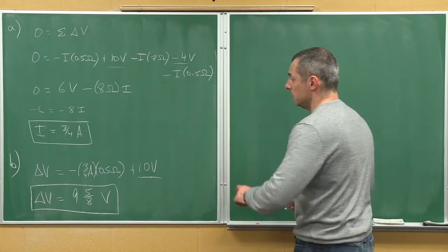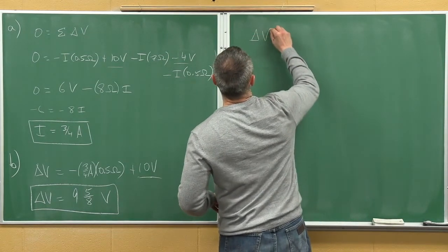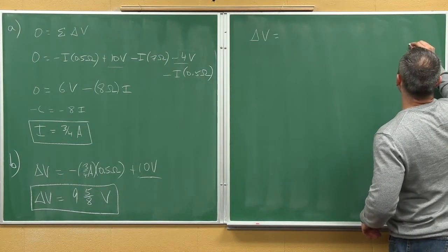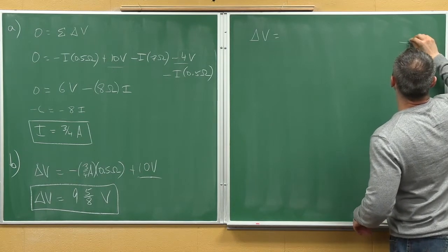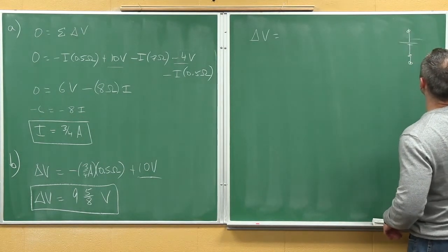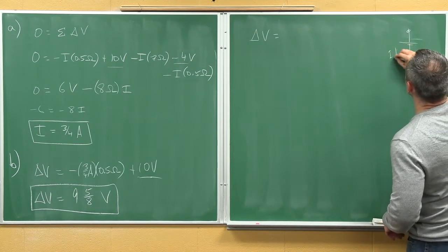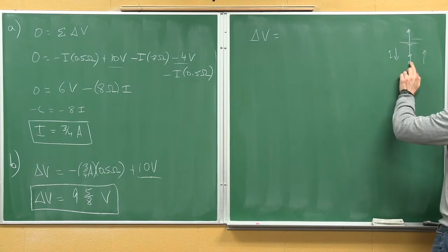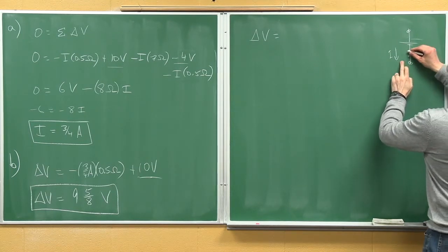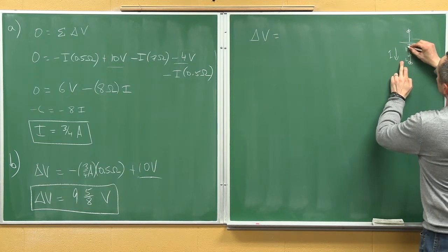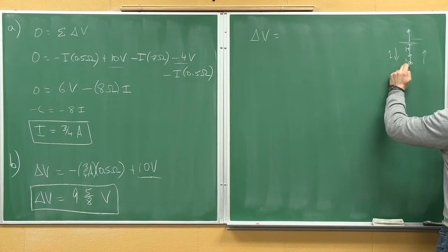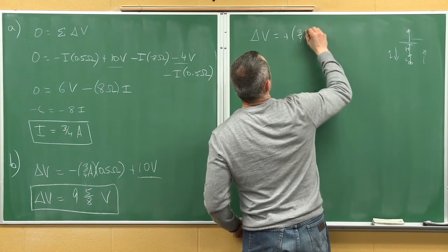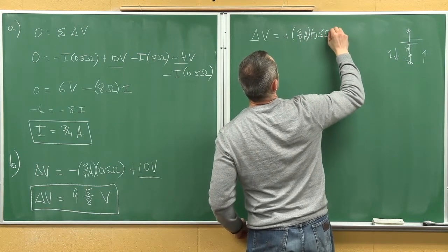So the next thing is the terminal voltage of the other battery, the 4-volt battery. And again, this is now a little awkward because I had to erase it, but this is what we saw. And let's suppose the ant is going to tally going this way, but the current is going this way. So the first thing the ant's going to encounter is this resistor. It's going uphill. This has got to be high volts. This is low volts, because that's the way the current goes, from high to low volts. So we go plus IR, plus 3/4 of an amp times 0.5 ohms.